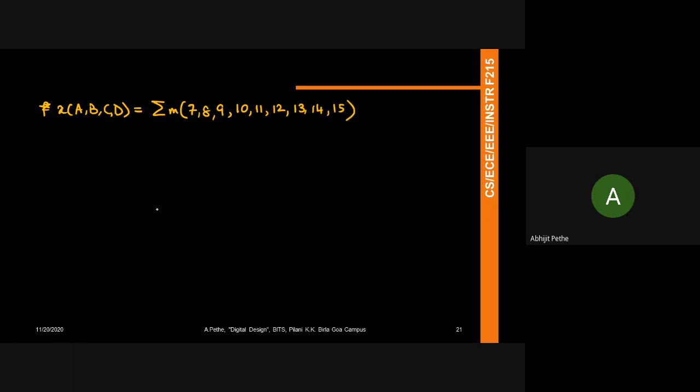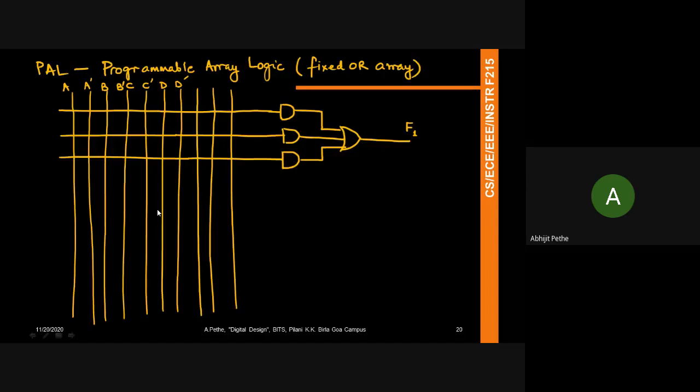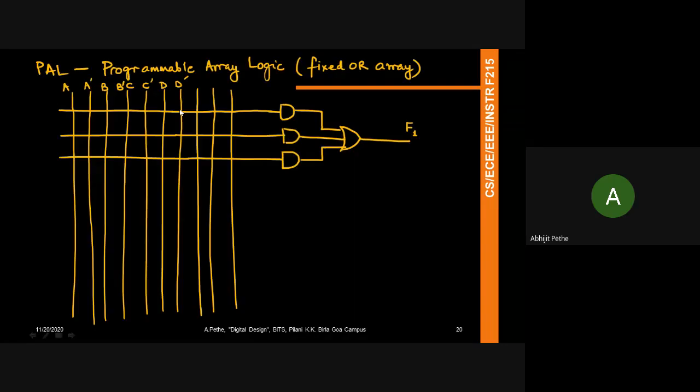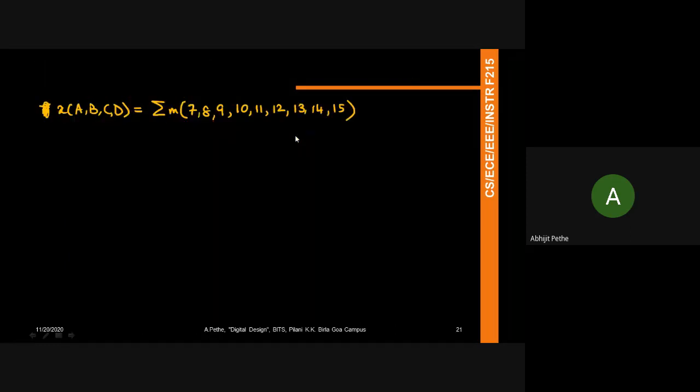So suppose I want to implement this in that first part of the PAL. How do I go about doing that? Can somebody tell me what the minimized form of this is? Obviously this is a bunch of minterms, and we don't have the flexibility. So you don't see all the minterms; you have to figure out what inputs I need to connect to this function. Can somebody minimize this and tell me what the expression is? Remember, A is MSB, D is LSB.